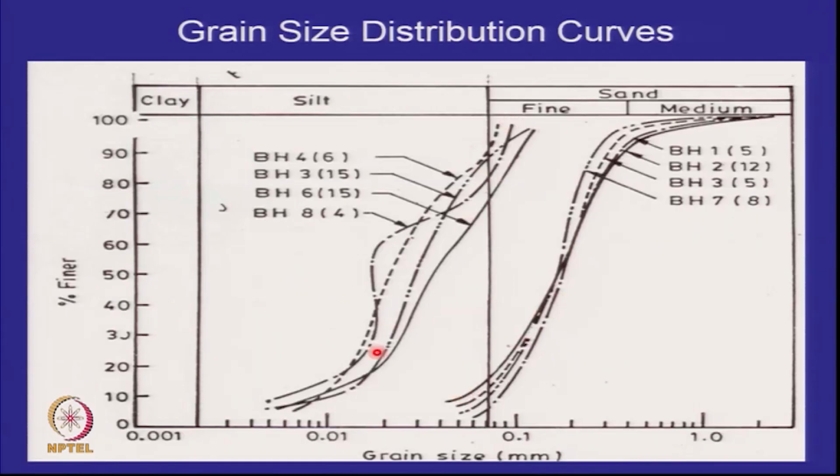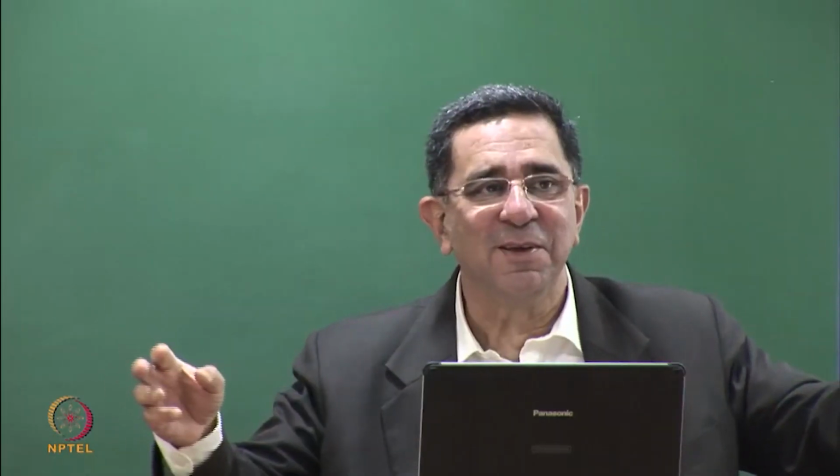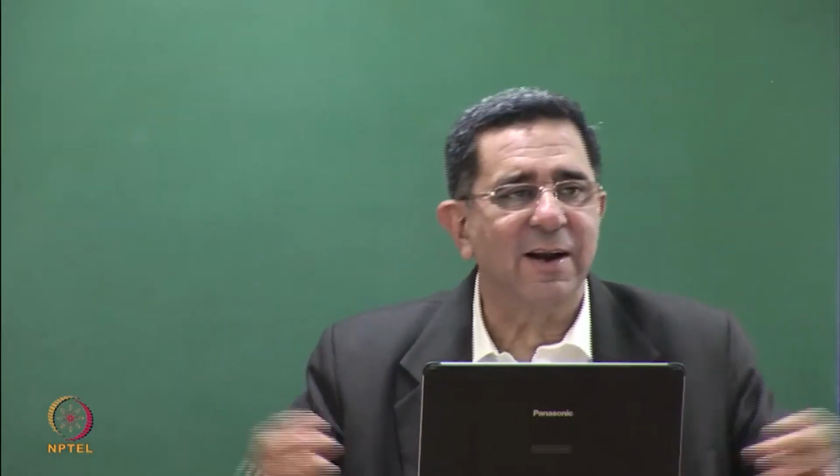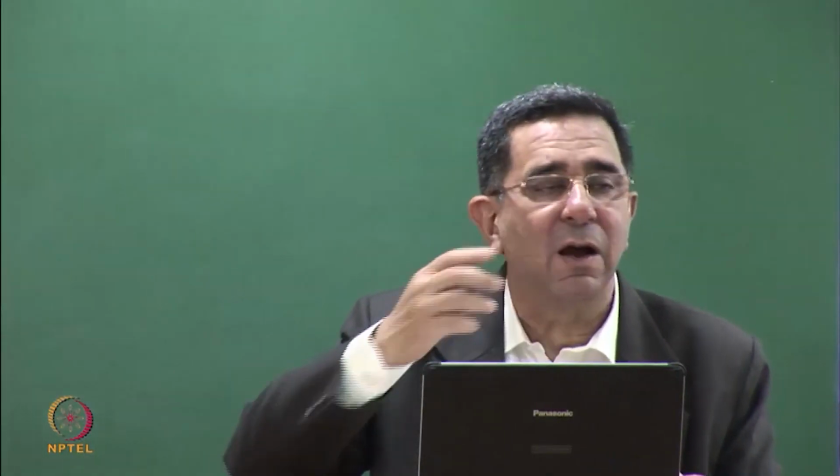So in a sense, you had fly ash in 6 fields. We mix them together, we send them to the ash pond. The ash pond again sorts them. The coarser comes here and the finer comes there. It is not sacrosanct. It depends on how your inflow point is changing. As I told you, it's a garland arrangement. So if the inflow point comes very close to the outflow point, you are going to have coarse material there as well.